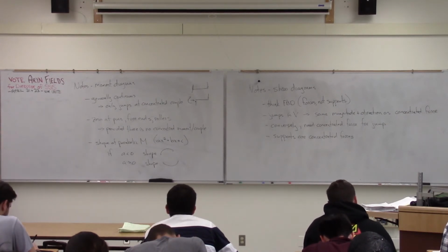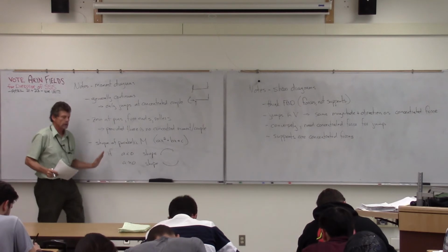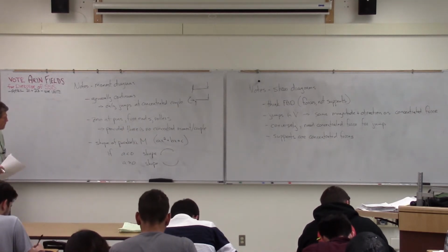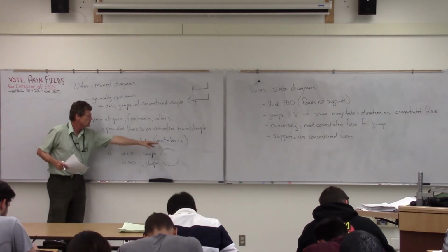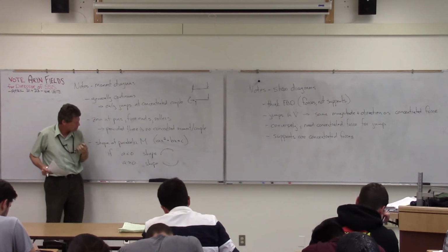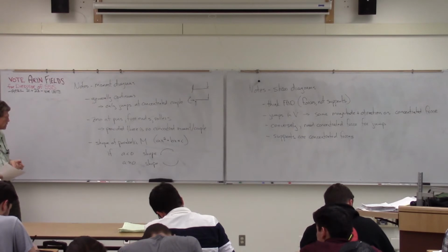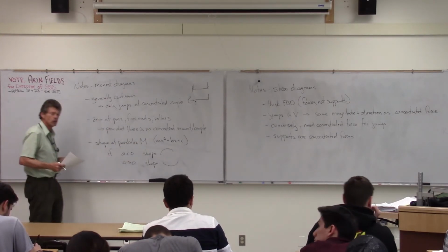You'll lose points if you draw the shape wrong. If it's negative, then what you've got is a positive moment, basically going over the hump and that sort of thing. If the coefficient in front of the x squared term is positive, then we've got a moment diagram that's shaped like that.